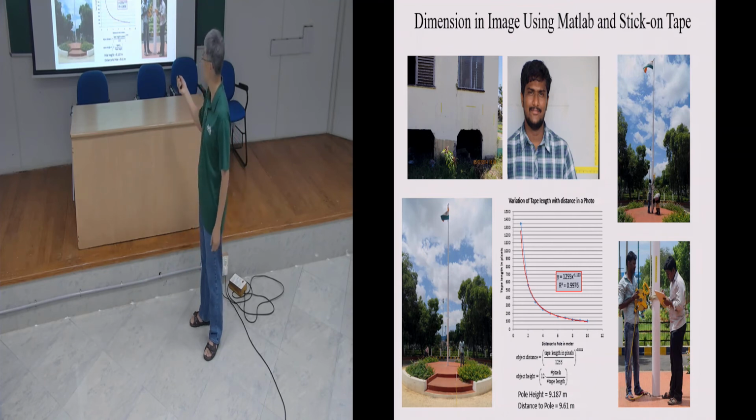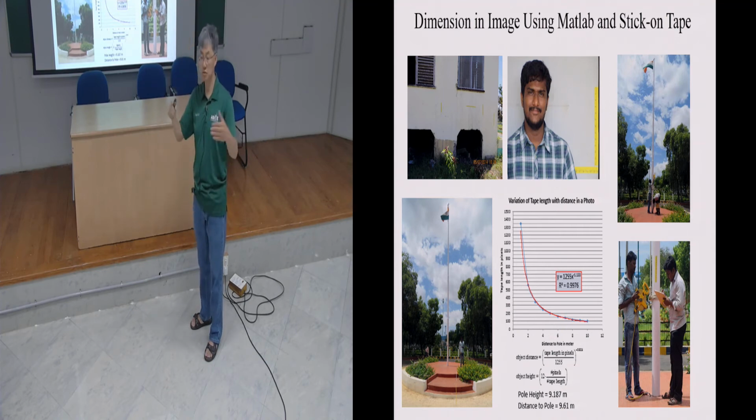So we brought this yellow tape to the Philippines, and we put it on the wall so that we can have a reference. Because with all the buildings, you don't know how they are designed. You don't know the height of the ceiling. But if you have this, you can use that as a reference to measure. So in this case, you see how many we have put. You can tell the dimension of the structure, and then you can quantify what the damage is.